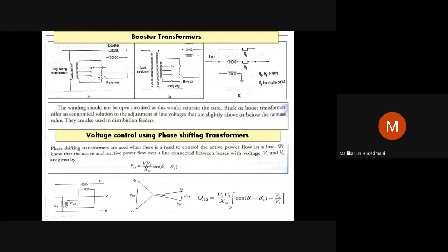That is making the resultant VR as VR dash. We are modifying the phase of R, which is VR at a certain position. That position by an angle alpha got shifted. That shift is brought by injecting voltage into this line by the voltage of the remaining lines Y and B. So this vector which is shown downward results in VR as VR dash. When VR is shifted to VR dash, what is the angular shift you got? This is called alpha. This is called phase shifting of a certain phase.